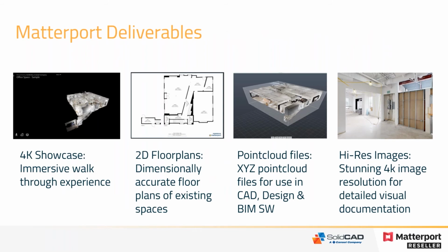What you can get out of your Matterport scans, again, is that 4K walkthrough, the showcase. I think many of you have already seen some of those samples in the gallery. We can also export 2D dimensional plans, schematically correct, and eventually those floor plans can be imported into AutoCAD. We can also get the point cloud data as an XYZ point cloud format, which is open source, and which we're going to show you in Recap, the point cloud registration software by Autodesk, to prepare it for importing into AutoCAD or Revit.